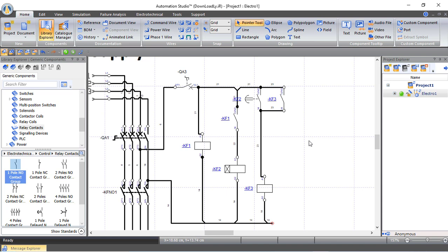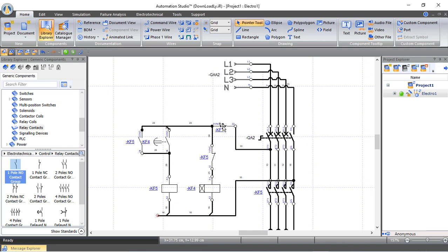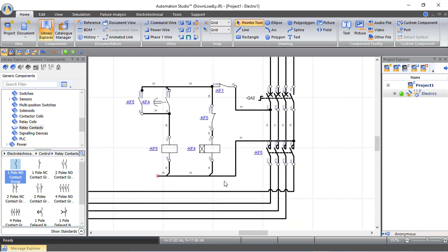Now what if there is an outage inside this circuit? Now this relay will be opened. So it will become normally closed here. So the power will start supplying this circuit. This on delay timer will start counting. Let's say for example we give it 10 seconds. So after 10 seconds it will close the circuit to make this contactor closed, and this will be latched for continuous working of this coil. So the contactor will be working, so our generator will start to supply our circuit.